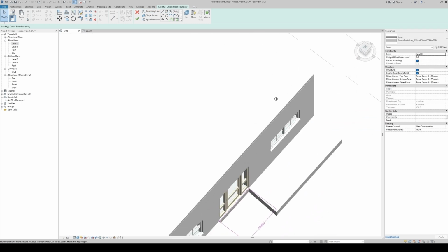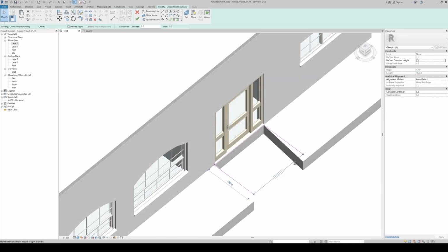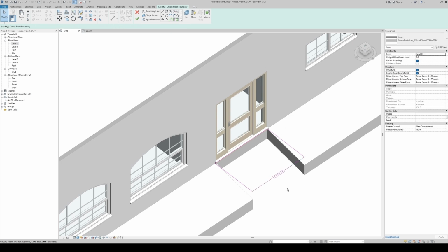So you see, by default, Revit has given us this line which has two parallel lines on either side. This indicates the span direction. So your floor is going to be supported on this and this line. If I delete this and try creating one boundary line here again, you notice Revit is creating a span symbol because that is necessary.